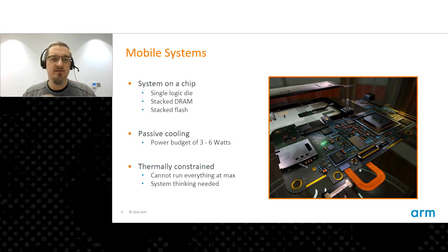But it does mean that all of the heat generating components are in one place in the device, right? And every watt of energy you put into this to drive the electronics is energy that comes out as thermal waste that we have to get out of the device. And by far the biggest challenge for high performance mobile is these are passively cooled devices, right? You'll have a heatsink, a thin heat spreader. High-end devices may have heat pipes that link that into the device case to spread the heat, but you're not talking half a pound of copper and a fan. So the biggest challenge is you can only run these as fast as you can passively get the heat out of those devices. And users make this difficult, right?